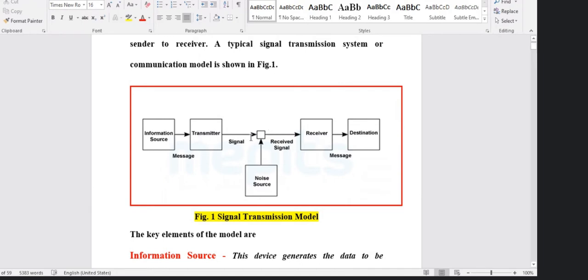So when we send them through the same communication channel, at the receiving end, instead of getting 5 separate voice signals, we will get a composite signal, which is why it is known as composite, because voice frequencies more or less occupy the same frequency band. So we couldn't distinguish one signal from the other. We are getting a mixed signal at the receiving end.